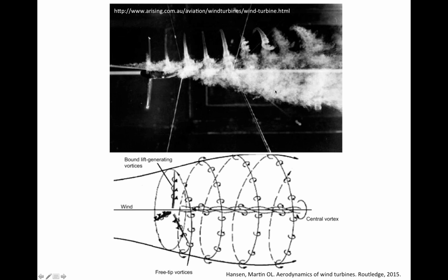For wind turbines, because the blades have finite length, tip loss also occurs near the tips of the blades of the wind turbine. Unlike airplanes that move along a straight path, the rotational motion of the blades creates vortex sheets of free vortices. Those free vortices are oriented in a helical path behind the rotor.